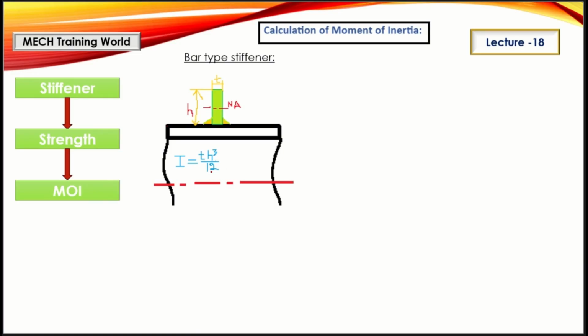By seeing this formula, you can say that the moment of inertia is based on the cube of the width of the cross section, guys. Depending upon the orientation, this moment of inertia will also decide the strength of the stiffener. So you need to consider in which orientation you are placing the stiffener, as that will also create a major change in our design, guys.